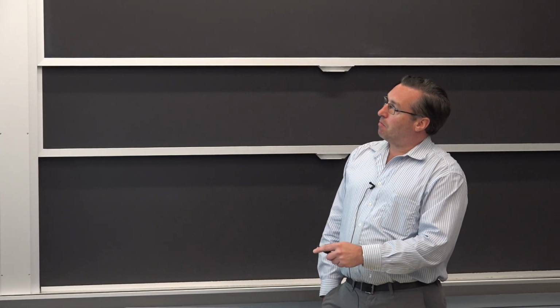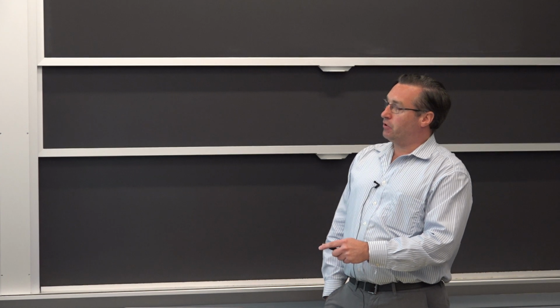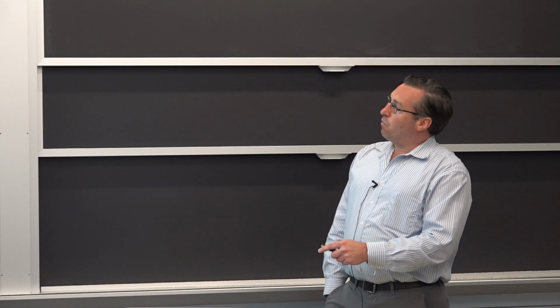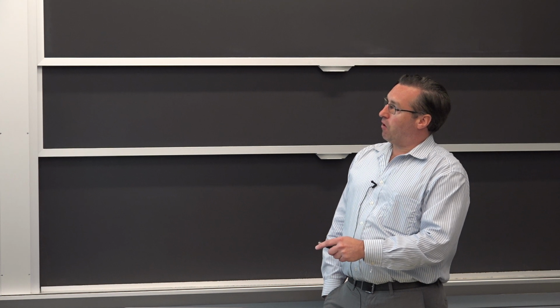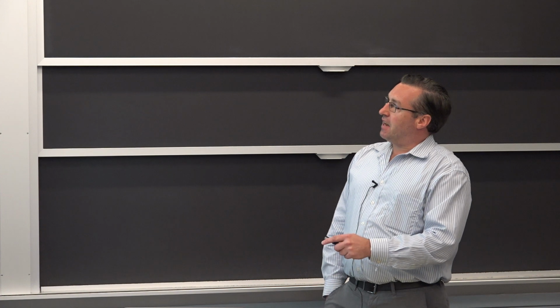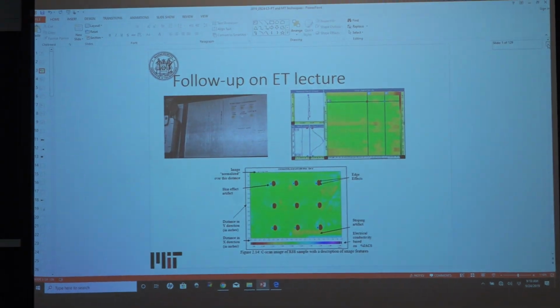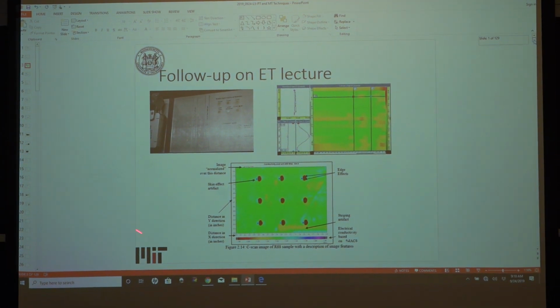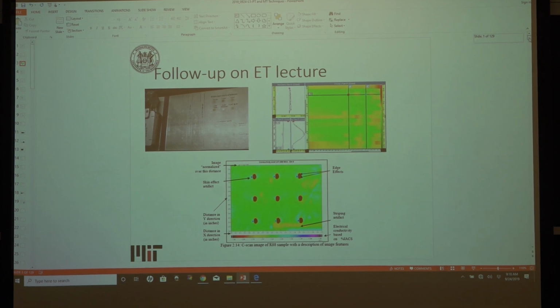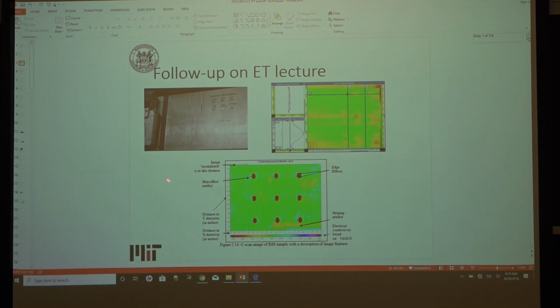This was a commercially available 32-channel array. One of the issues that you see is the difference with just a 32-channel array that does not collect data simultaneously. So there's 32 channels that collect 32 pieces of information, as opposed to what's known as the meandering winding magnetometer, which can have more than 32 channels, but it's the way in which the data is collected and the way in which the data is normalized.